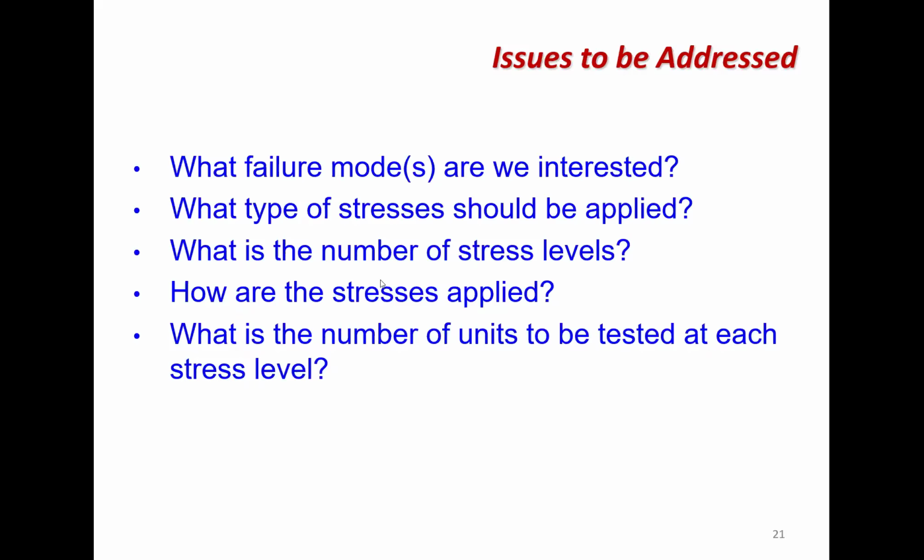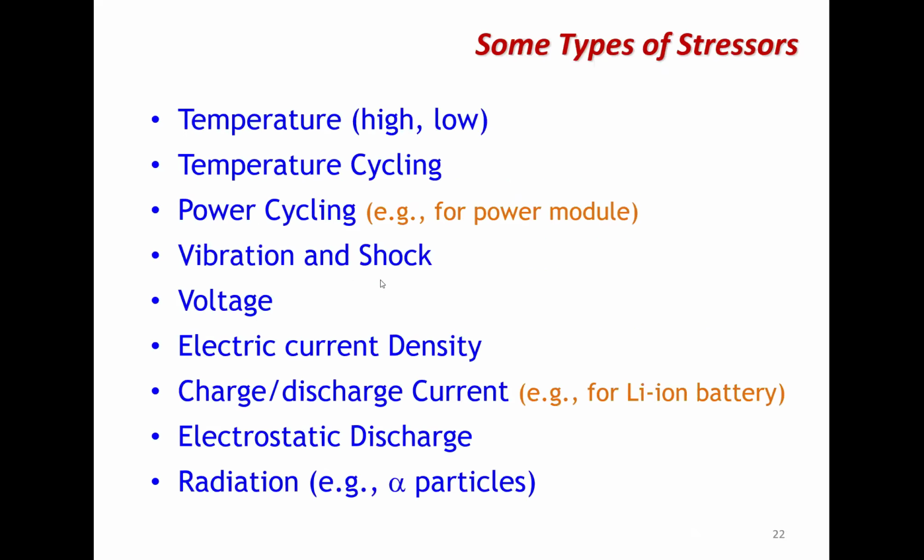So you talk about this. So these are some very practical problems a test engineer faces every day when they do reliability tests. Now, regarding the types of stressors widely used in reliability testing, we mainly consider temperature, high and low, and temperature cycling, and power cycling, especially for those power modules.